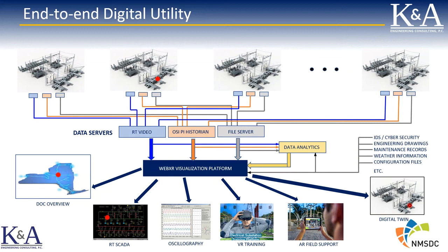You have a real-time SCADA operator looking at a screen like the single line diagram there. He'll be informed of the event as well. And post event, you can have your engineering team call up and retrieve the oscillography files that completely describe the event and can be used for forensics analysis.